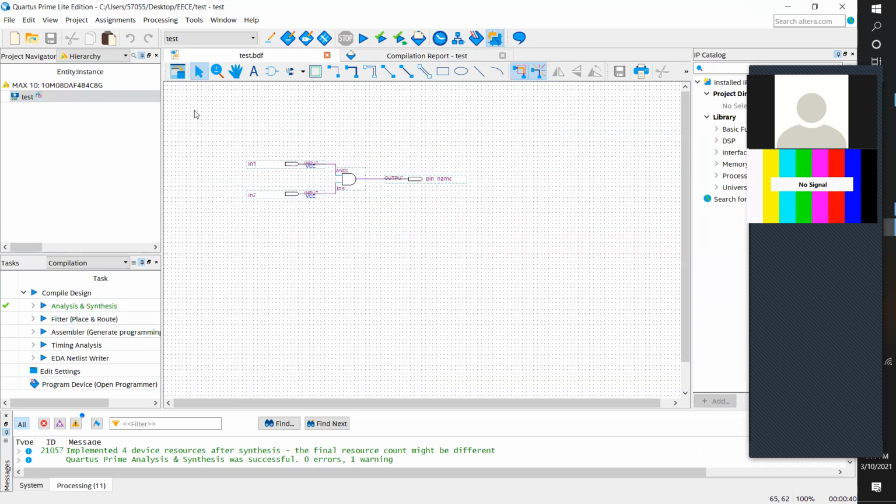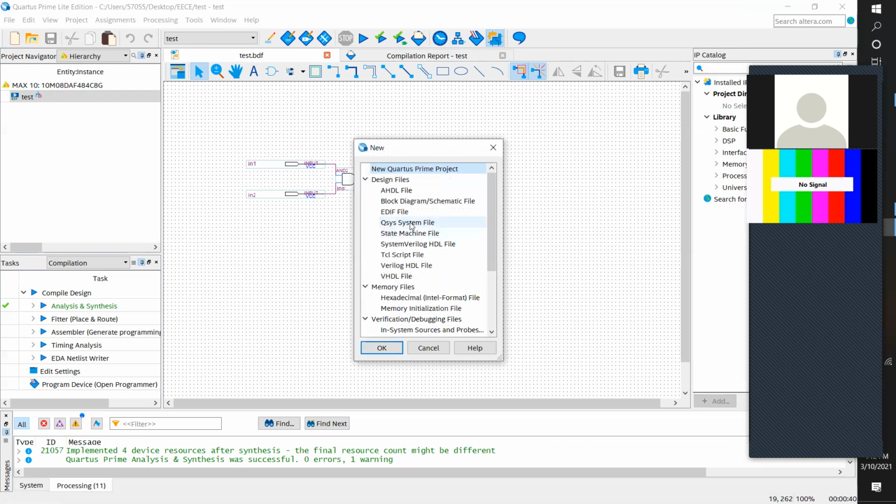There are many ways to do this. The one way in the tutorial is to use VWF. If you want to do the simulation, you have to make sure that you install ModelSim. I will just show you what happens if we don't have ModelSim.